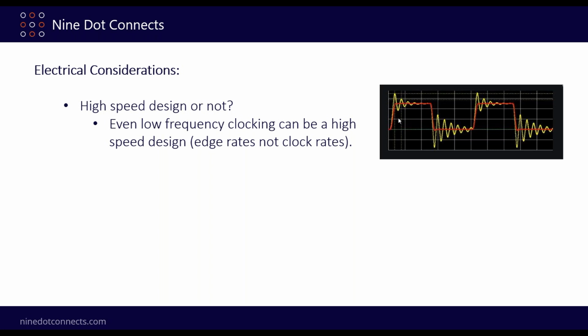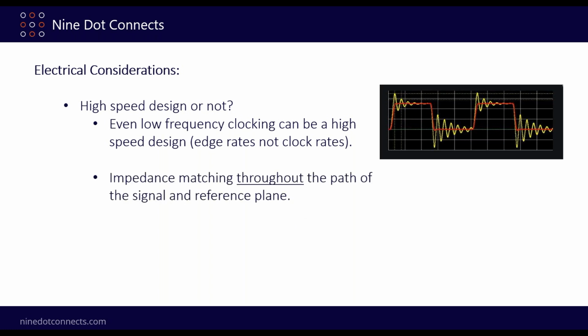They can make them cheaper by making them smaller. And by making them smaller, they become faster. And so you can get very fast edge rates. And if you're not treating even low data rate signals correctly, you're going to get all kinds of signal integrity issues. You're going to get EMI issues. You're getting all this frequency element of this thing. So always consider whether this is a high-speed design or not, and always tend toward high speed, even if it doesn't seem like it.